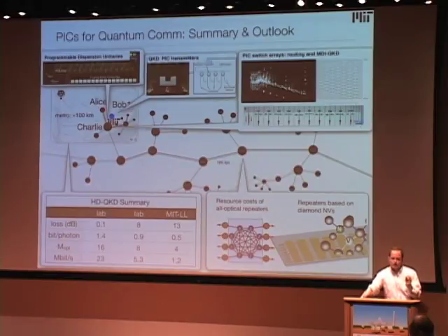There's some recent ways that you can actually heavily bias silicon photonics to make directly an electro-optic modulator that looks promising, that could push down these losses and still give you the same speed. The devices that we're developing now for the NV centers are based on aluminum nitride, which has a Chi2 coefficient and is directly usable as modulators. And in their case, there should be no loss. There's no free carrier dispersion. But the downside is that the modulators tend to be a little bit bigger. So this is for high-speed modulators. Typically, with high speed, I think you're going to incur some amount of loss.